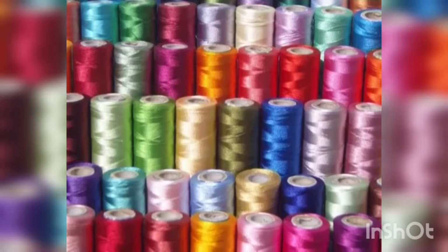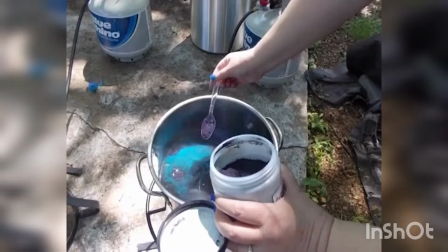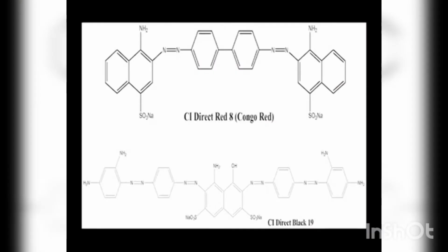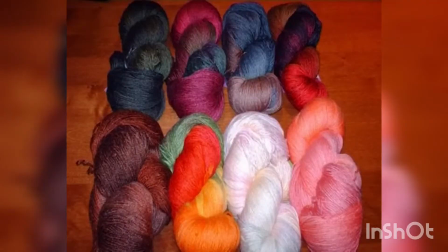and fast colors. When acid dyes are used, dyeing starts at 40 to 50 degrees centigrade. The temperature is gradually raised to 85 degrees centigrade in about 45 minutes and maintained at that temperature for that period. After dyeing, the silk is rinsed and washed in water made slightly acidic with acetic and formic acid. A fresh dyeing with basic dyes has the effect of giving deeper and richer shades.